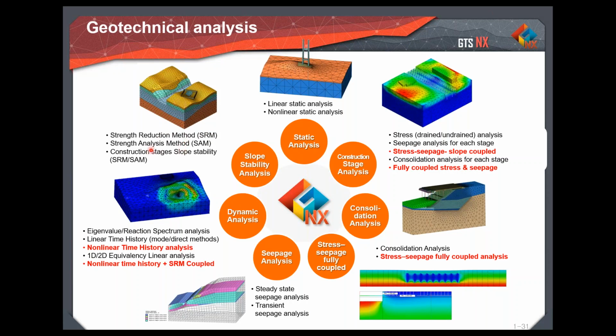And we also have another method called the strength analysis method, SEAM. This is a combination of both your finite element method and your limit equilibrium method. All the slip circles will be taken, and the failure surface will be calculated based on FEM, and the slip circles will be incorporated. Basically, the stresses will be calculated using FEM, and the failure surface will be developed based on the limit equilibrium method. So that's the strength analysis method for you.